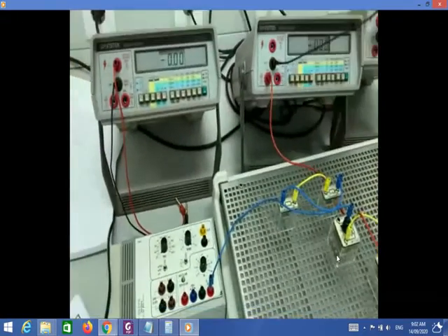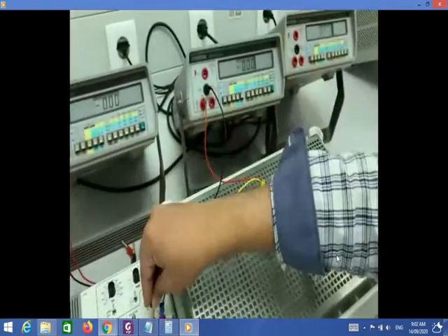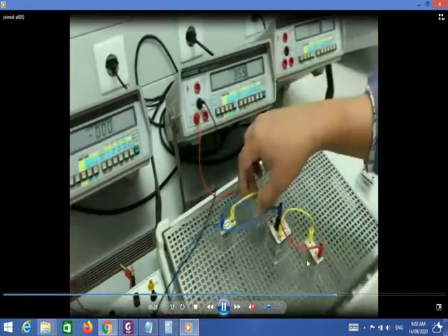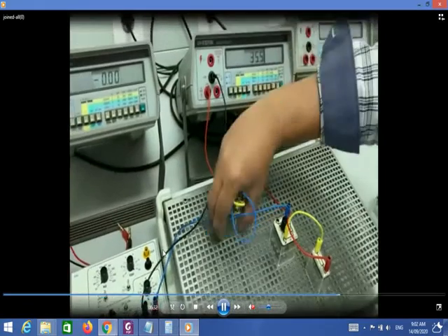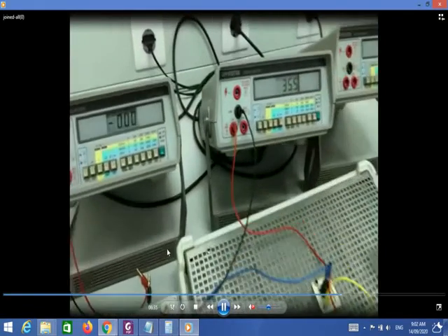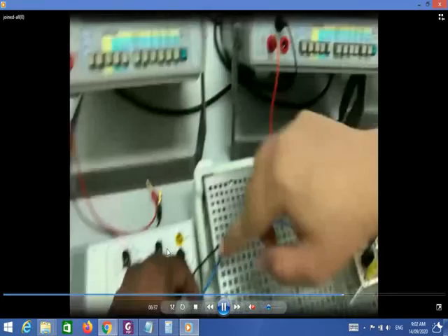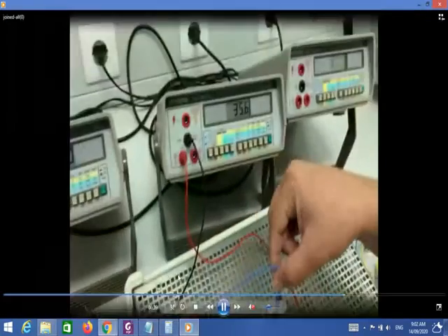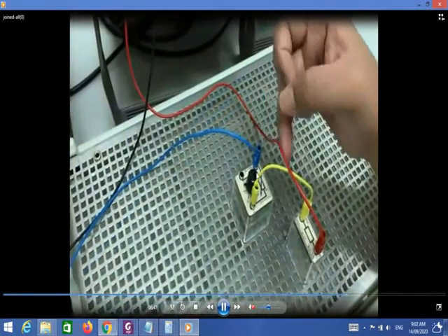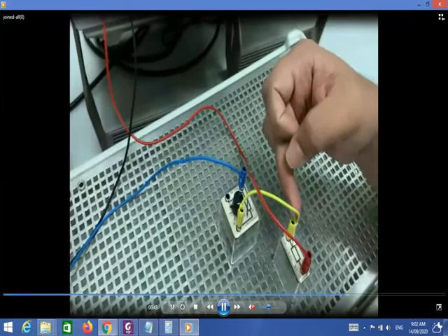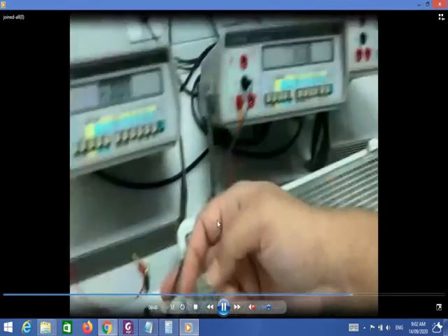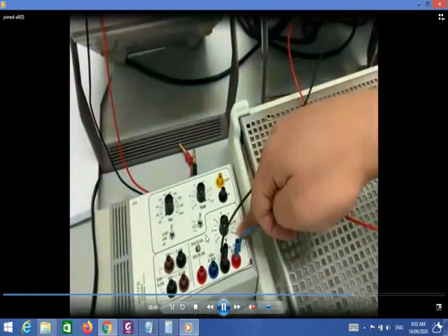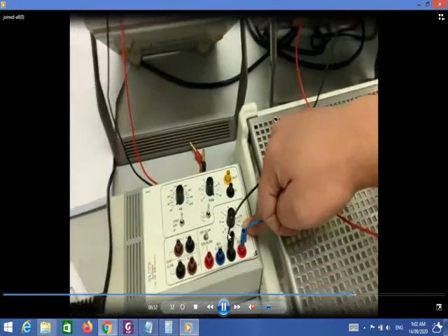This R L has to be connected to the ammeter, then the ammeter is grounded. We'll remove these unnecessary components to avoid confusion. After giving this connection from V Thevenin to R Thevenin, and from R Thevenin to the load resistance, connected to the ammeter, which is grounded, we got the value we set, 10 volts, which is V Thevenin.